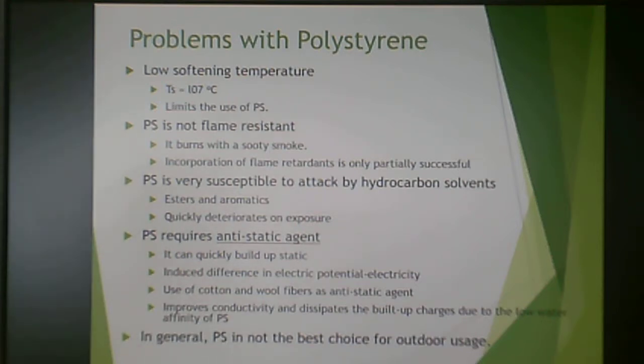Polystyrene also requires an anti-static agent. It very quickly builds up static, and oftentimes they use cotton and wool fibers as an anti-static agent in the formulation. It improves the conductivity and dissipates the charge due to the low water affinity of polystyrene. Generally, you're not going to use polystyrene for any outdoor applications because of the susceptibility to UV attack.